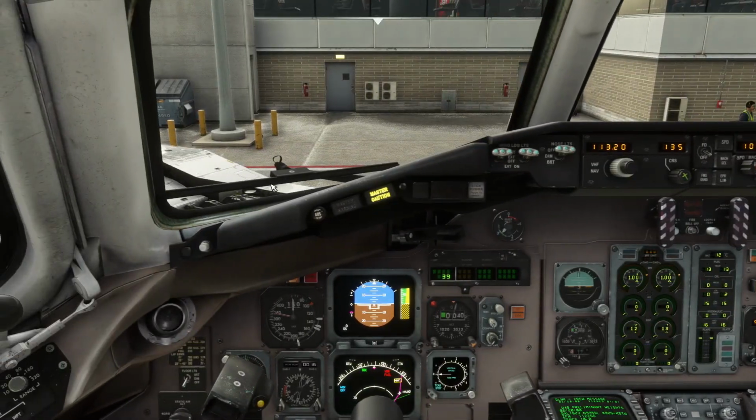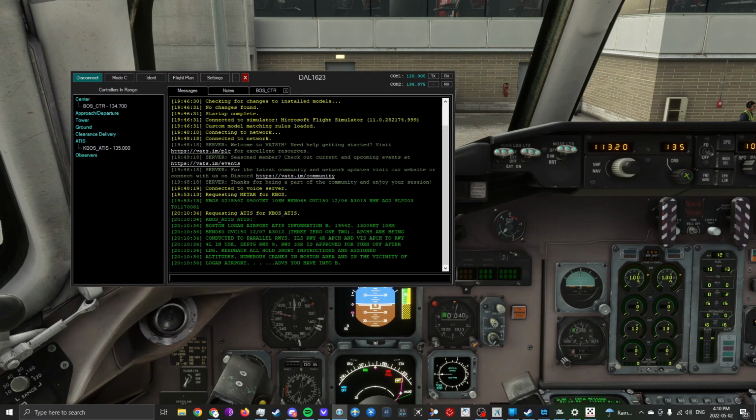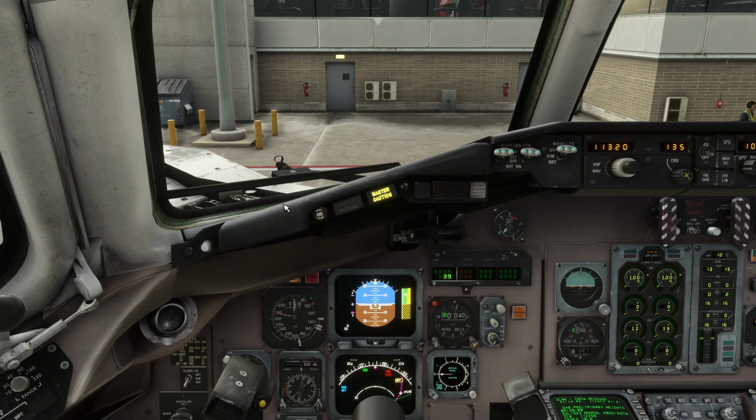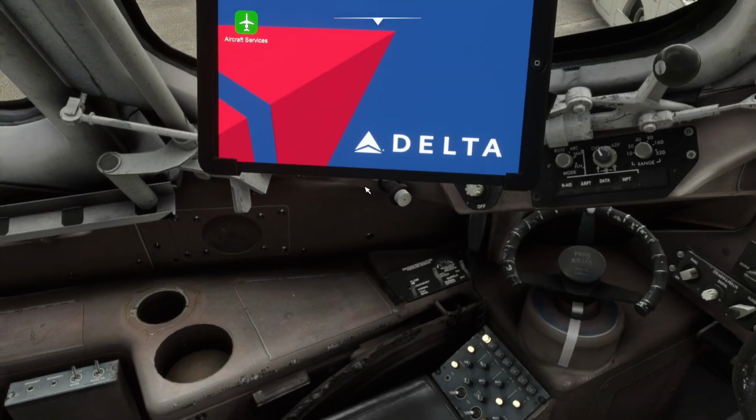So, next thing we've got to do, let's see here. I am just going to check the ATIS. Sorry, I forgot Center's online, so that means there's ATIS. Information Bravo. I'm going to disregard all the weather information because we already have that. Departing runway 9. Okay, so we're good. Now we're going to set up the instruments for departure.